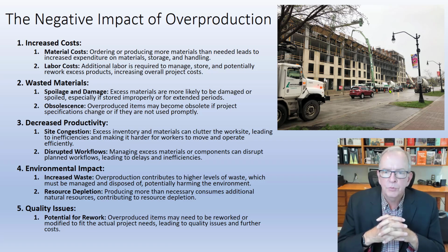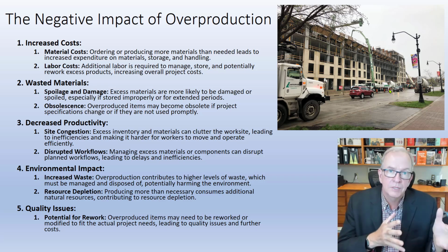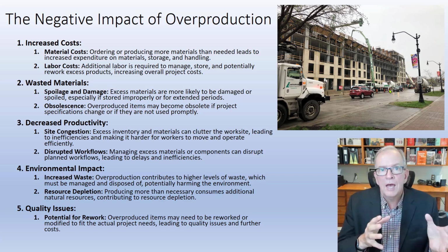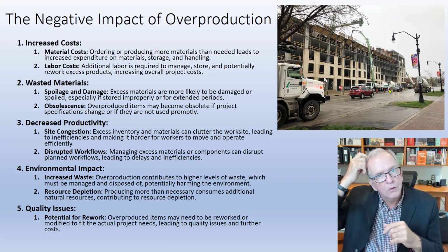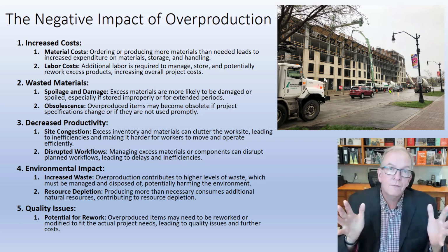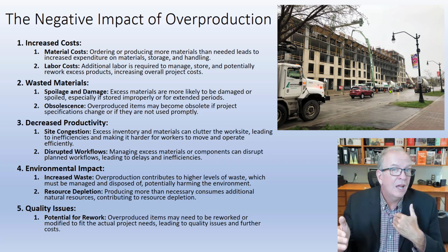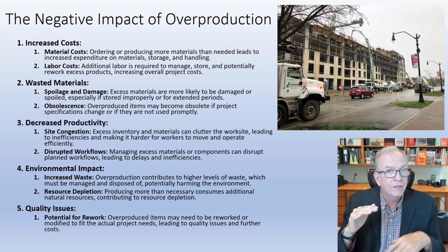basically here we need 10 cubic meters of concrete, when the reality is we only need 9 cubic meters of concrete. That's a big waste, right? That's a very big waste. It's 10%, but it's also the actual waste that goes into getting rid of that extra cubic meter of concrete, and how that is done becomes a problem. Or on the other side, you excavated more than you needed to, and then you've just ordered extra concrete to make up that difference in fill. So that's a waste, because now you've got more concrete than you needed.